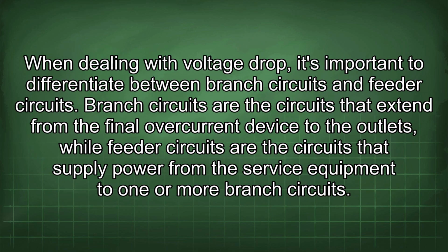When dealing with voltage drop, it's important to differentiate between branch circuits and feeder circuits. Branch circuits are the circuits that extend from the final overcurrent device to the outlets, while feeder circuits are the circuits that supply power from the service equipment to one or more branch circuits.